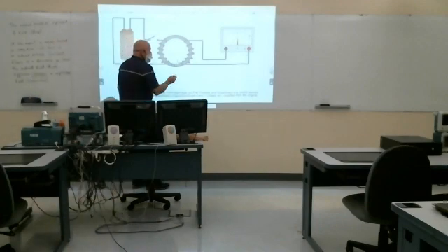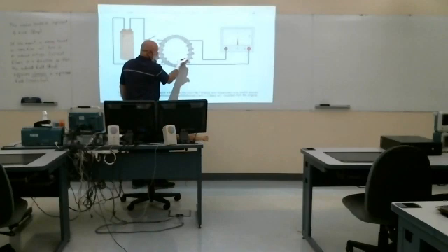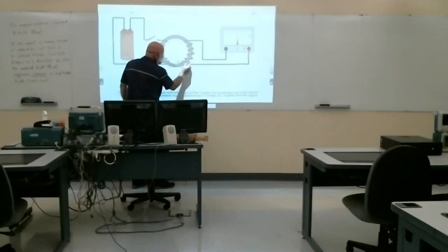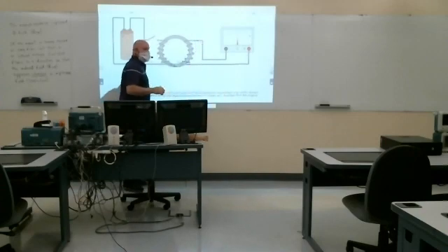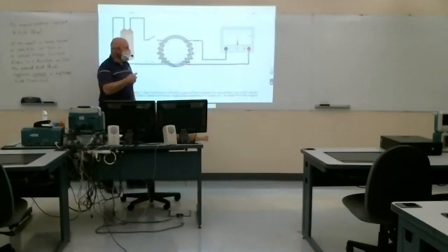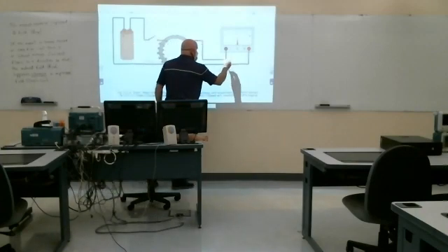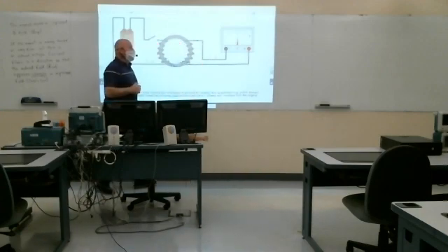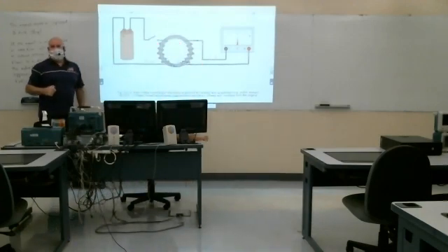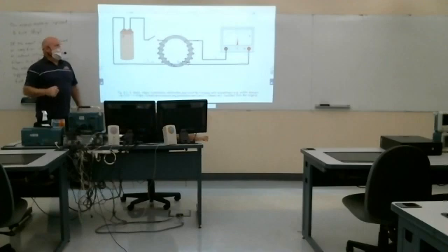which means in this case, my coils here, my field lines are inside my coil, so my current has to be in this direction, which means it has to be coming out of the top of the coil. So view that as a voltage source here. That means this is plus, this is minus, which means now as I hook up my voltmeter, it would swing to the left. And I'd see a negative voltage on my voltmeter.